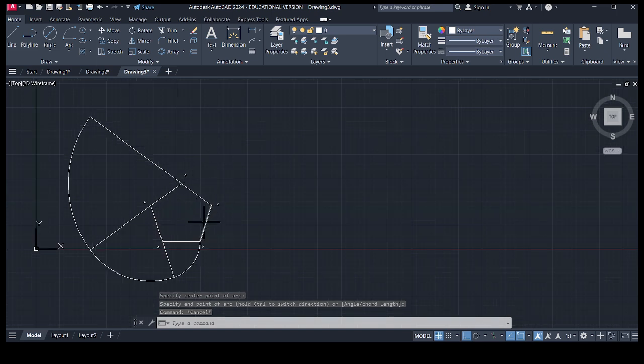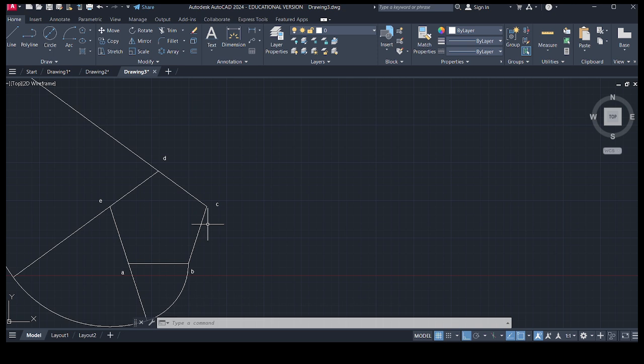And now BC is the edge length through which we have to draw the line. Select that edge at point C, locate your mouse cursor, select the option lengthen. How much distance?